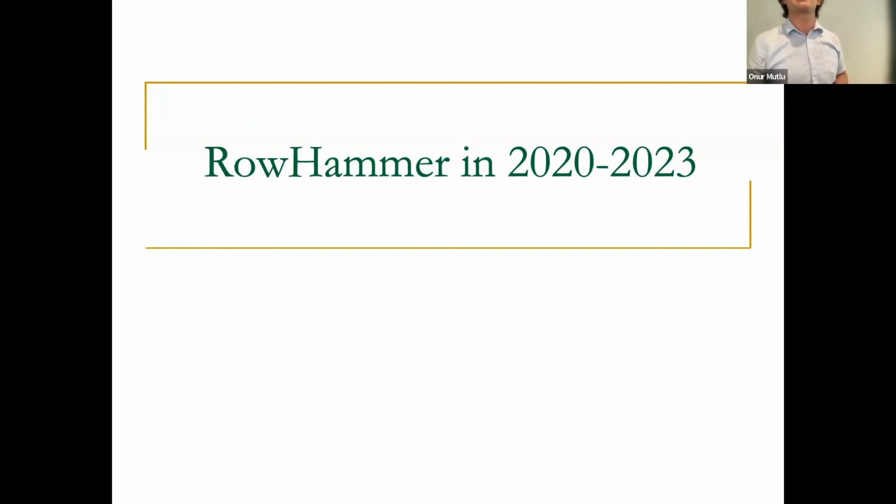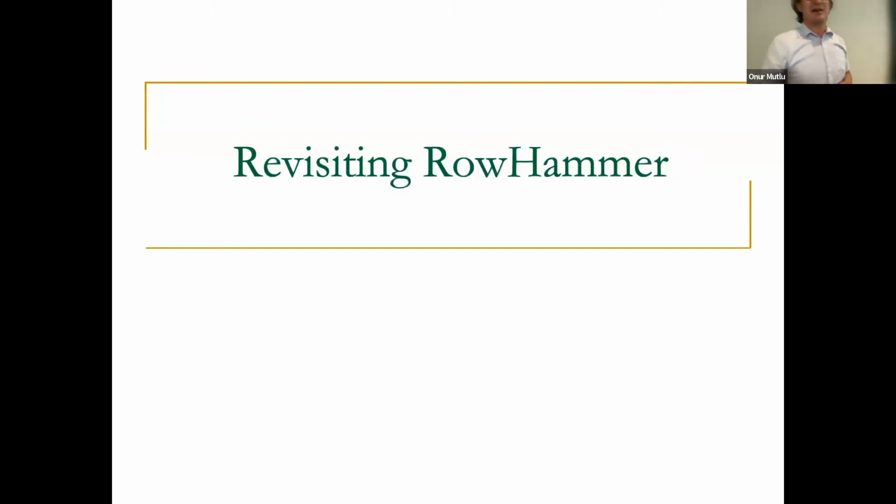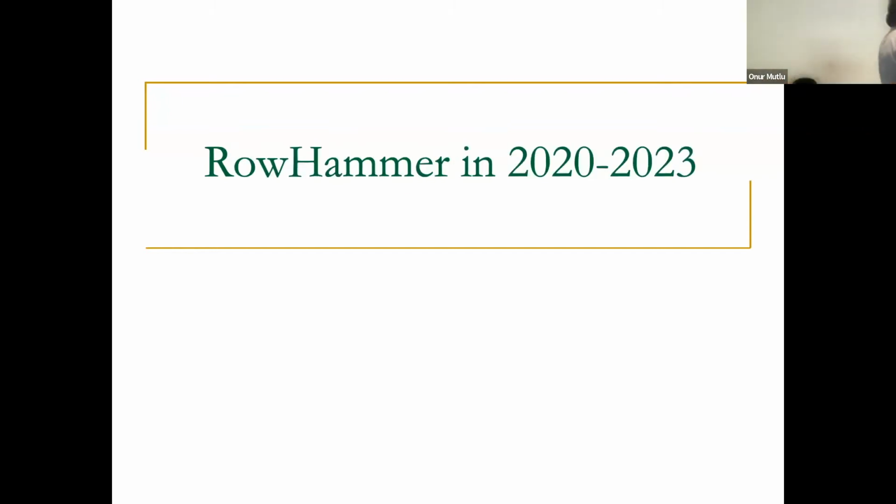These are great questions. So what happened basically? Intel actually had this solution, but Intel turned off the solution because DRAM manufacturers around 2018, 2017 through 2019 claimed that they actually solved RowHammer. They basically said, our DDR4 chips are RowHammer free. You don't need to have these solutions in your memory controller. And that's essentially what happened.